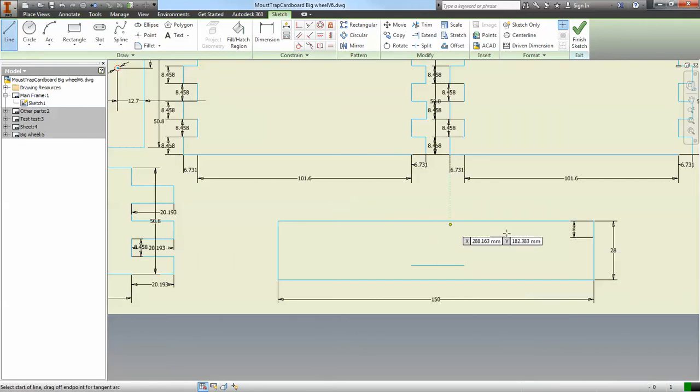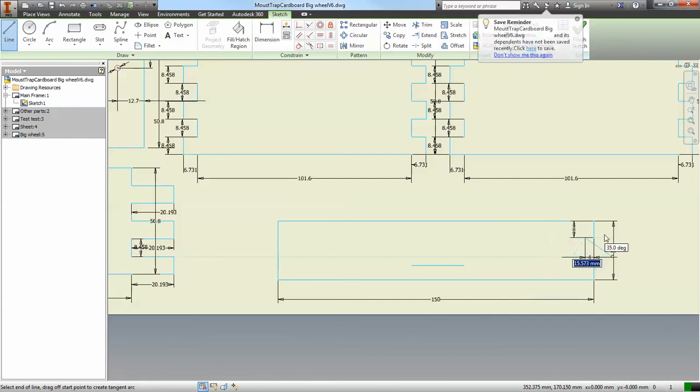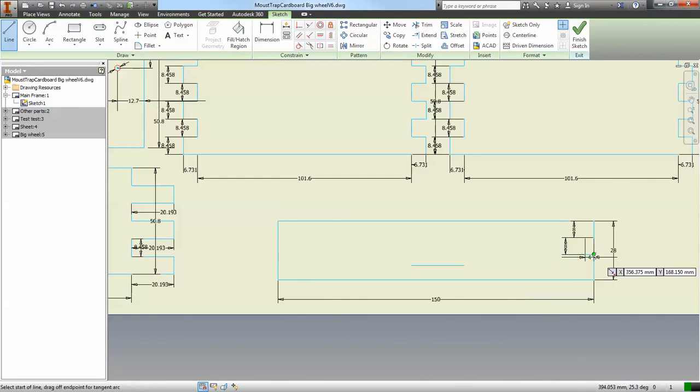you're going to draw a line from that point in, and let's say we want it to be 4. Okay, and then we want to draw a line from there, and we want that to be 8 again. So we're going to type in 8 and then hit tab, and then we're going to click, and then we're going to come back in right to this line, and then we're going to draw our line down.